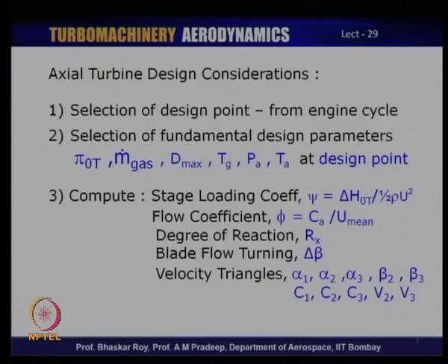As you know, in case of an impulse turbine, the degree of reaction indeed would be 0. That means all the static changes occur in the stator and no static change occurs in the rotor. On the other hand, most gas turbines that we are dealing with are reaction turbines. So, they have a positive reaction value, which as I mentioned varies from root to the tip of the rotor, or the inner diameter to the outer diameter of the annular space of the turbine.